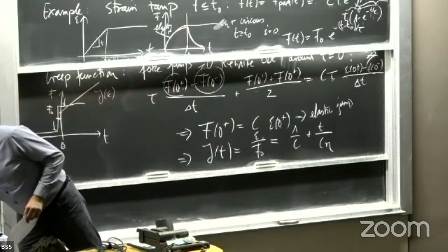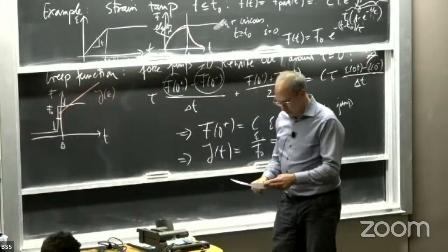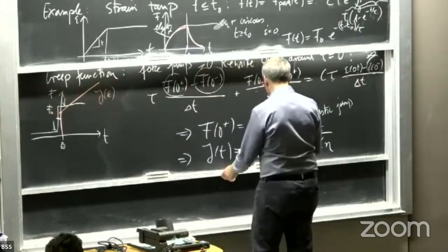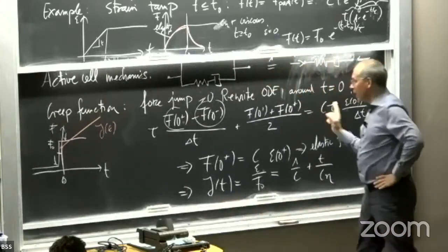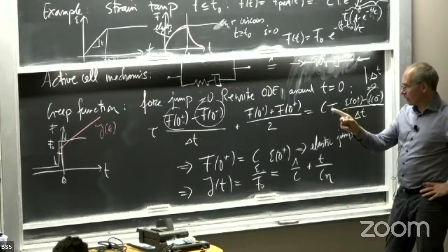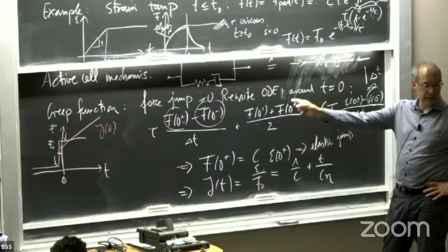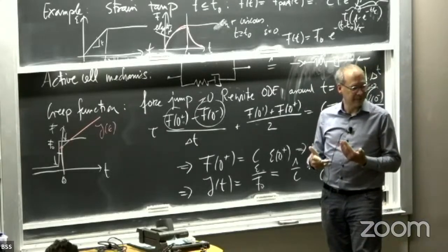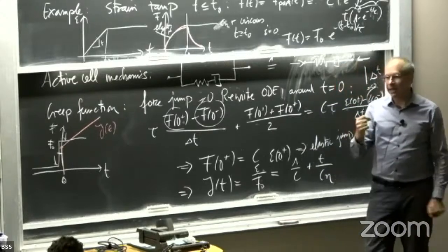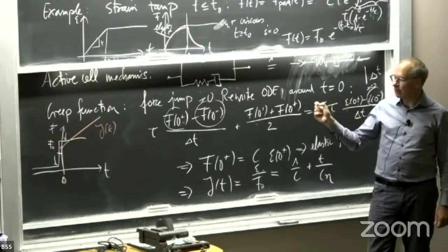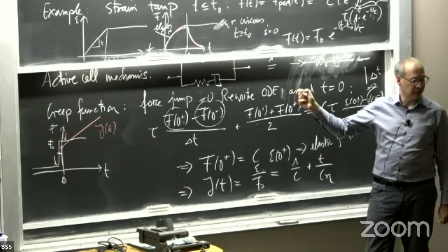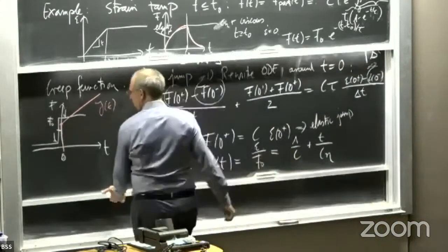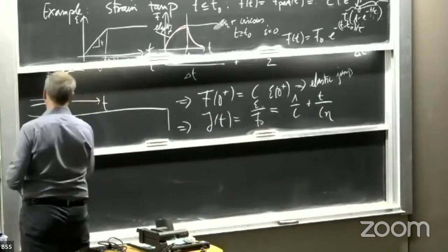So this is actually all I wanted to say about the Maxwell model. There's one interesting thing here. If you think about this, I have solved the same differential equation twice, once by fixing the right-hand side, once by fixing the left-hand side. And you might ask the question, shouldn't this be equivalent? It's the same equation, right? And the answer is yes, actually. So the creep function and the relaxation function are equivalent. All the information about the model is in both functions, both functions carry the same information.